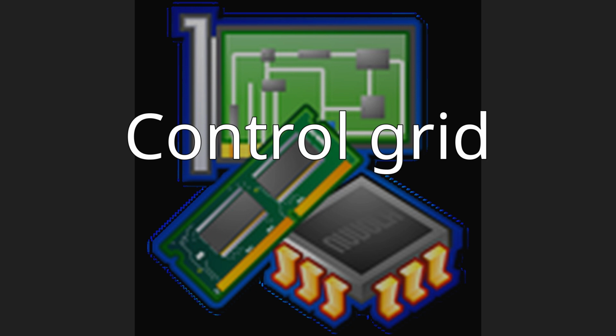Control grid. The control grid is an electrode used in amplifying thermionic valves (vacuum tubes), such as the triode, tetrode, and pentode, used to control the flow of electrons from the cathode to the anode (plate) electrode. The control grid usually consists of a cylindrical screen or helix of fine wire surrounding the cathode, and is surrounded in turn by the anode. The control grid was invented by Lee de Forest, who in 1906 added a grid to the Fleming valve (thermionic diode) to create the first amplifying vacuum tube.